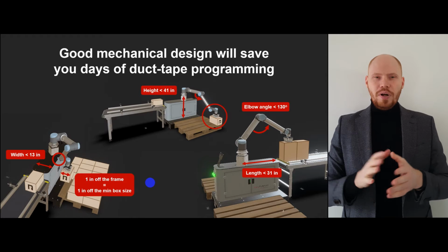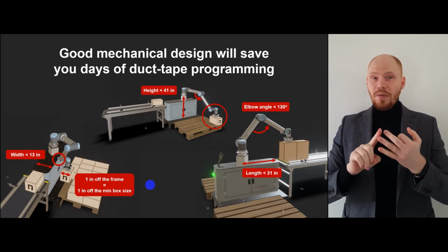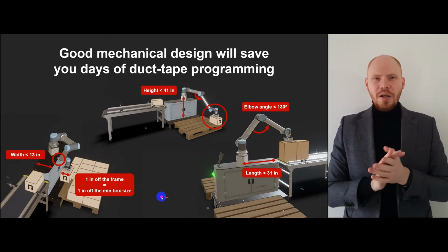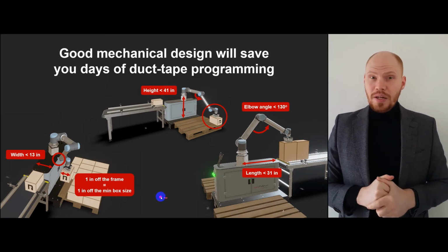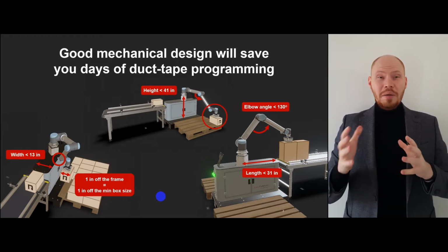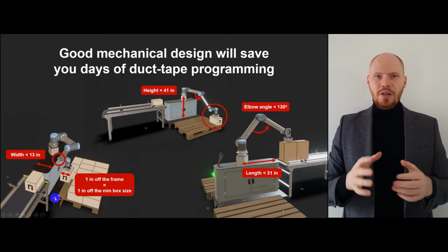With a mobile frame, you have to note three parameters: length, width, and height of your frame. The references I'll give you are approximate and also depend on your gripper and box size, but still quite useful. Similar frames can be used with fixed pedestals. Let's start with the width of your frame. It impacts the stability of your palletizer as well as possible wrist frame collisions.